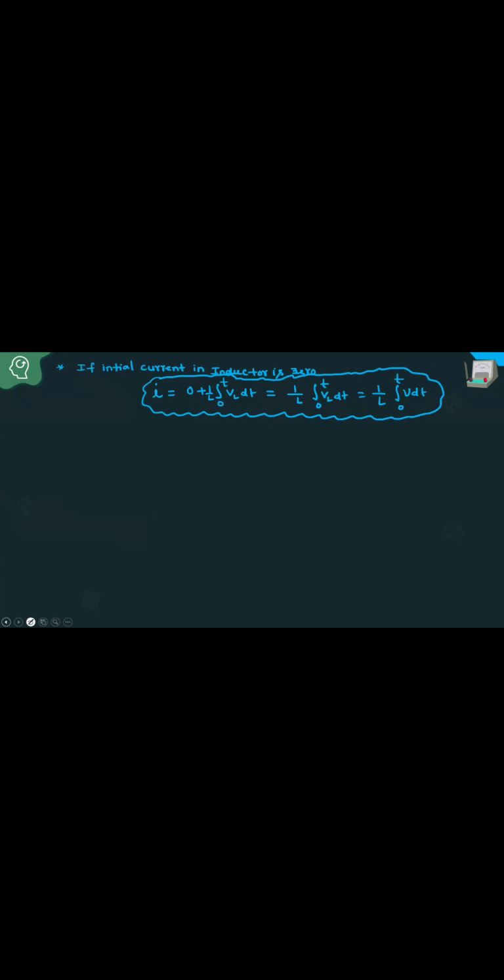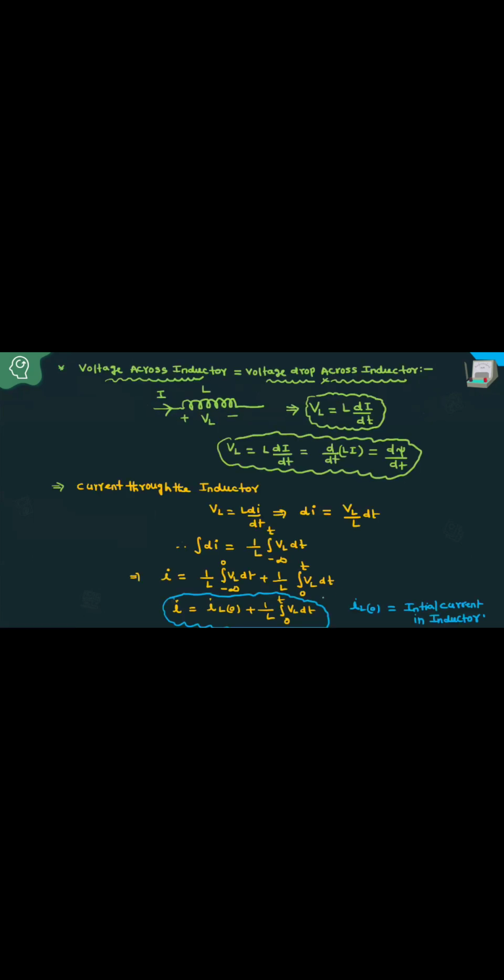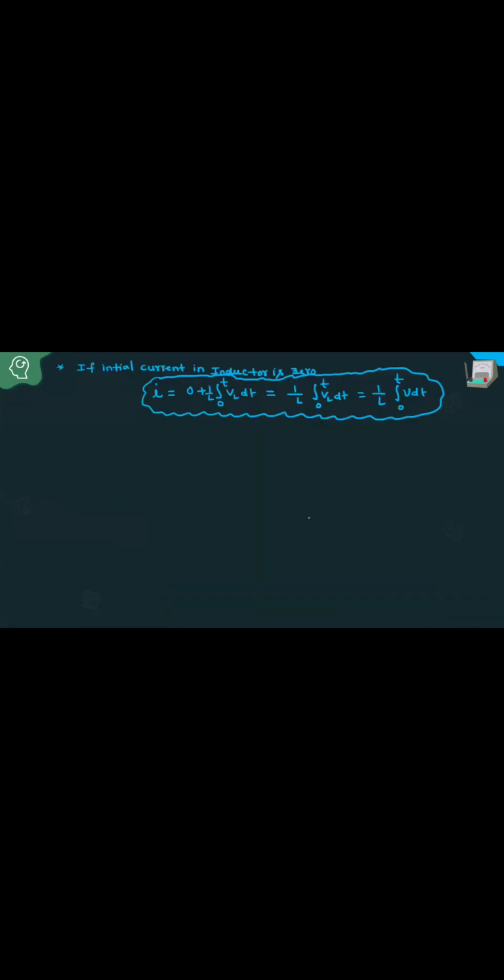That is how to write the expression for current through the inductor and the expression for voltage across the inductor. But now, here are some very important observations while solving problems. See, for example, this is note 1. During solving of problems based on these models, questions have already appeared in GATE and ESE. For example, we know that the voltage across the inductor VL equal to L into di by dt.